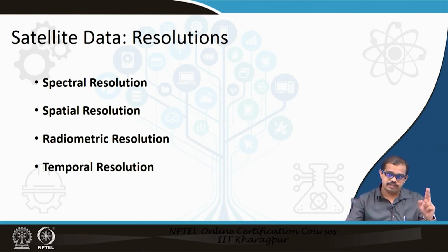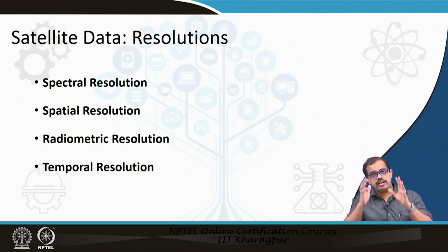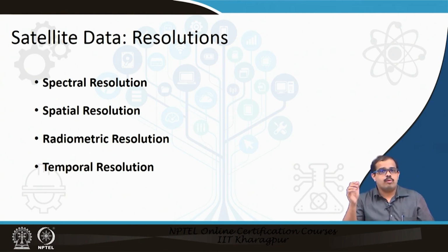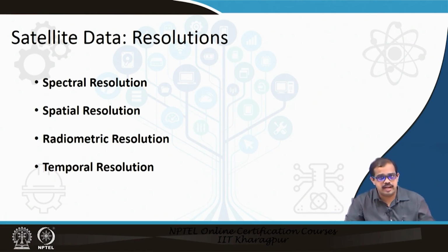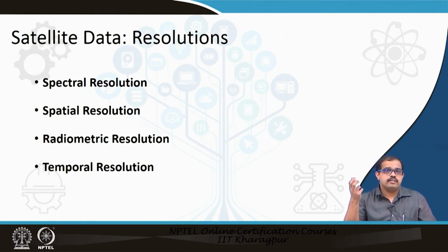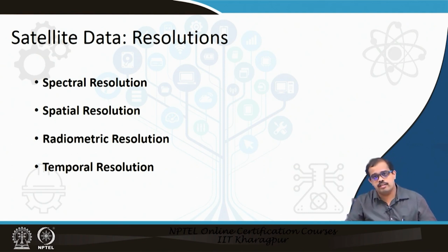If you do not have the data already with you, then before even considering any data, you should understand what kind of resolutions you need. Okay, for example, if someone is looking at how the growth of a city is happening, or trying to understand the city pattern, there is no need to buy very costly high spatial resolution data. But if someone wants to see building-wise or road-wise information of a particular city, then you need very high spatial resolution data.